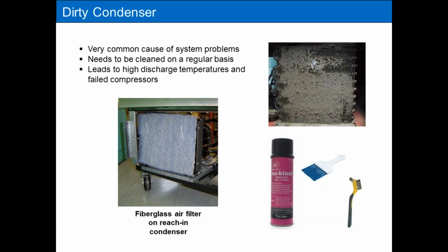Easy cleanup: pull it out, put a new one on, so that's very nice. It does make you have to go back on a regular basis to clean them, because these do get plugged up more frequently than just the coils. So you've got to tell your customers, if you're going to go to this approach, somebody needs to change these on a regular basis, because they will plug up faster and lead to a loss of airflow more quickly than if you didn't have it on. But if you do keep up on the maintenance, it's a quick cleanup, right? Change it out, put it on. So I like it from that point of view.